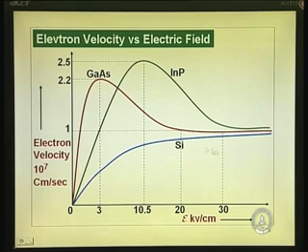In fact, I have seen some people degrading gallium arsenide, putting this slightly below this quantity. I do not believe that. It is almost the same, because after all the mechanism of transfer is the same. Indium phosphide has velocities higher than that of silicon over a wide range of field. Gallium arsenide has velocities higher than that of silicon over a certain field range. So, these things make quite a bit of difference in performance.